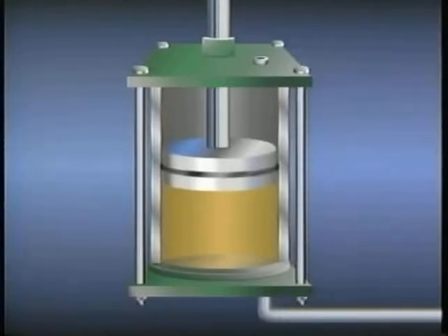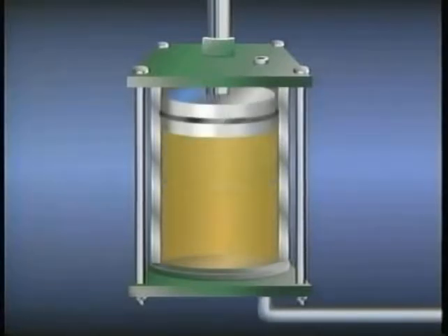This, in turn, moves a device or load that's normally attached to the end of the piston rod. The area on the other side of the piston is vented to atmosphere to prevent air from being trapped and compressed, which could restrict the movement of the actuator. When the flow of fluid stops, the piston and piston rod stop and are held in their new position by the fluid trapped under the piston.